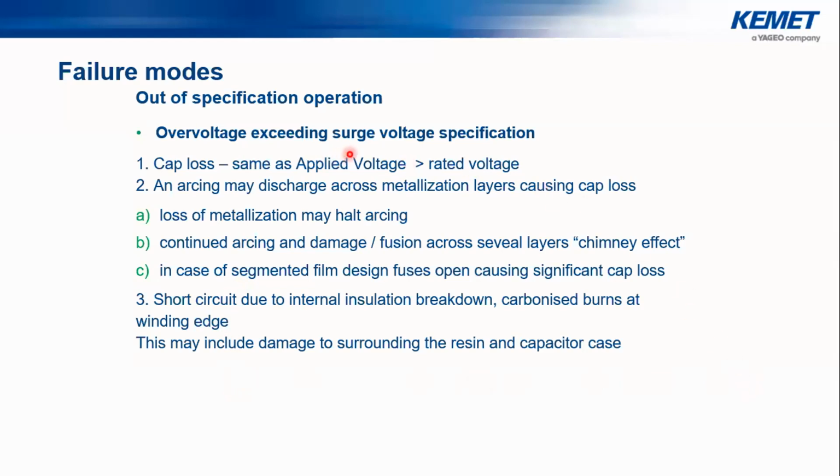So this is important when it comes to the overvoltages, and specifically don't consider, okay, we are allowed to have, for example, 1.5 times the rated voltage at the transients. Of course, you cannot expose the capacitors to so many transients. It's just limited. And if you have an application that is all the time going to be exposed to overvoltages, you can also kill the capacitors through this phenomenon.